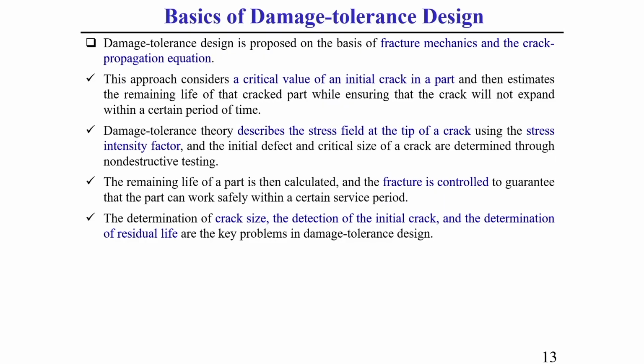Okay. We will now discuss another technique called the damage tolerance method. This is a very interesting method. Here this damage tolerance method is proposed on the basis of fracture mechanics, and here we also need to consider another aspect, that is the crack propagation equation. This approach generally considers a critical value of initial crack in a part. So, this is the main point, you should keep it in mind.